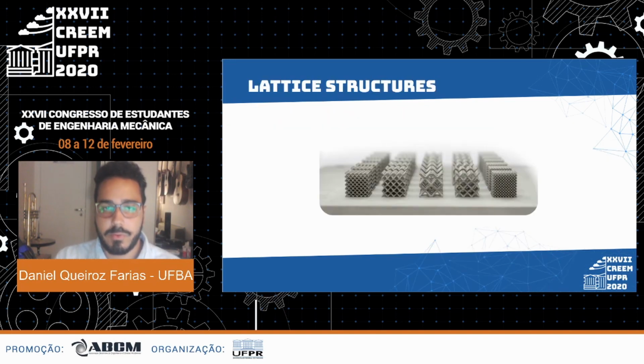The second topic approached in this presentation is lattice structures. According to McConaughey, lattice structures can be defined as topology-ordered, 3-dimensional open cell structures with strut elements connecting the cells through cell nodes, usually repeated in a specific pattern, and normally manufactured through additive manufacturing.